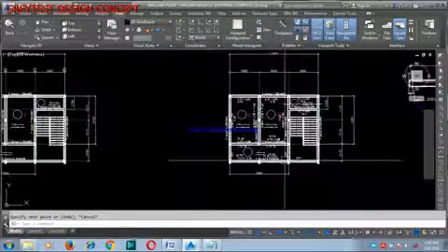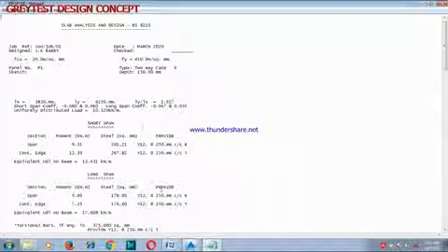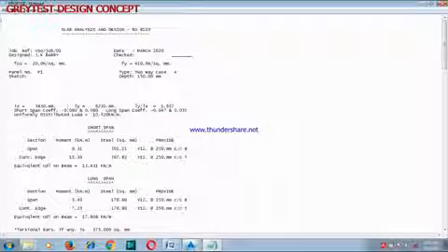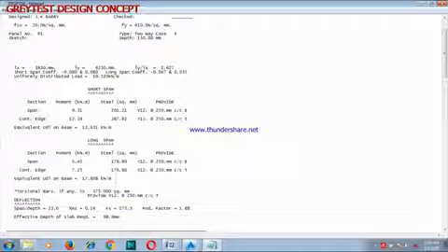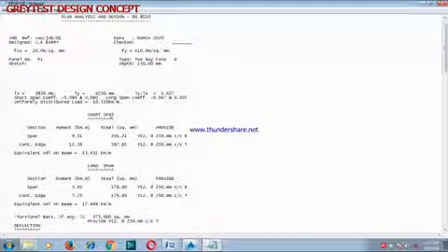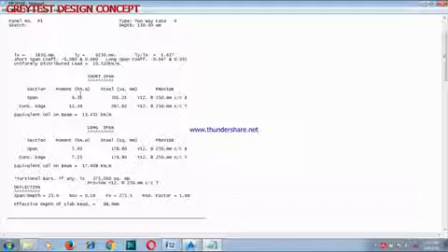Now the values we got from our slab calculation, or slab design rather, if you have been following that same GA, that value we got on panel 1, this is panel 1, on the shorter span, which is LX 3830.